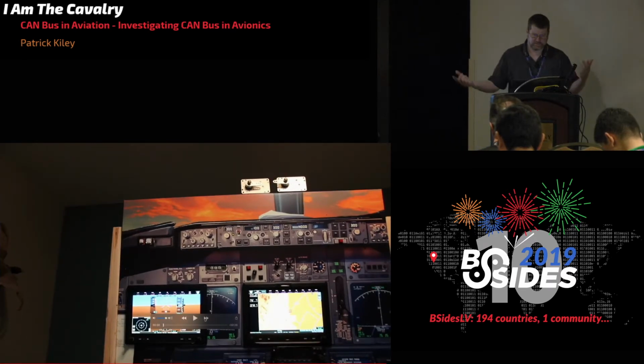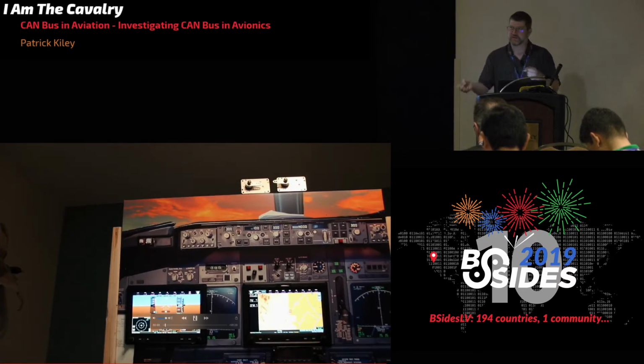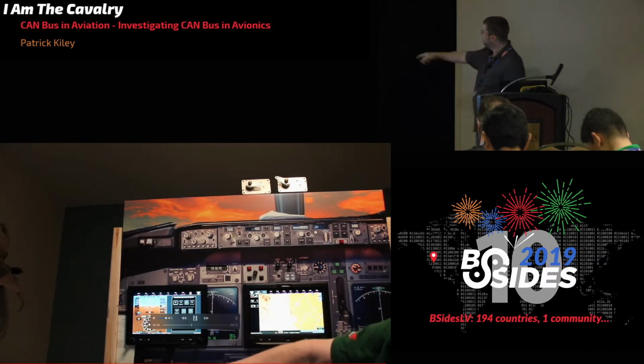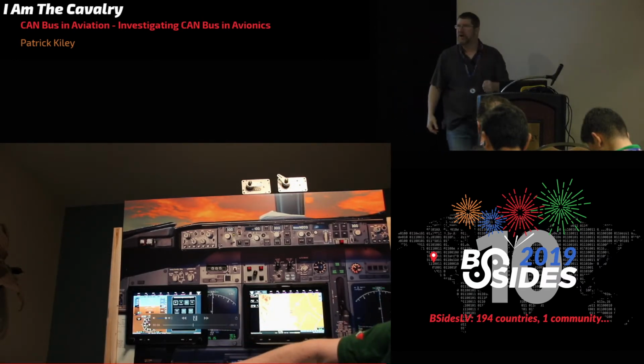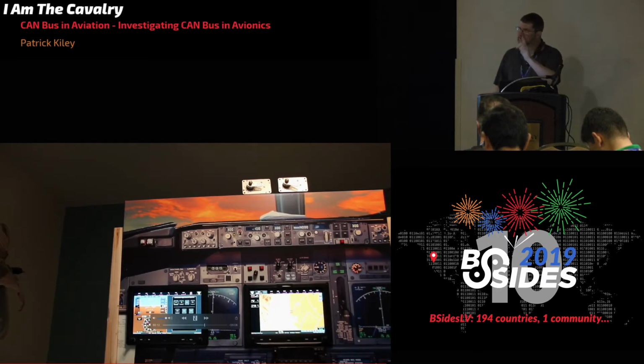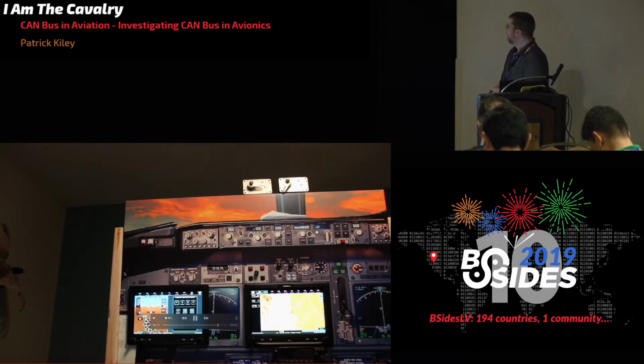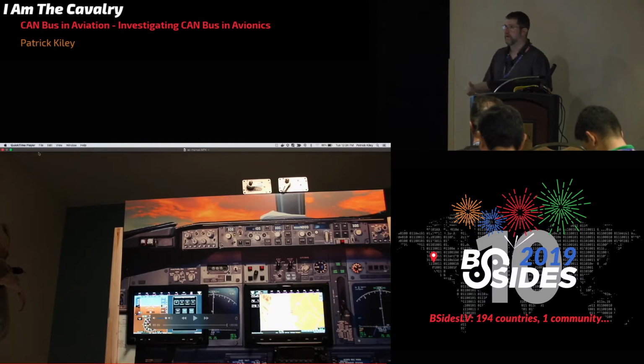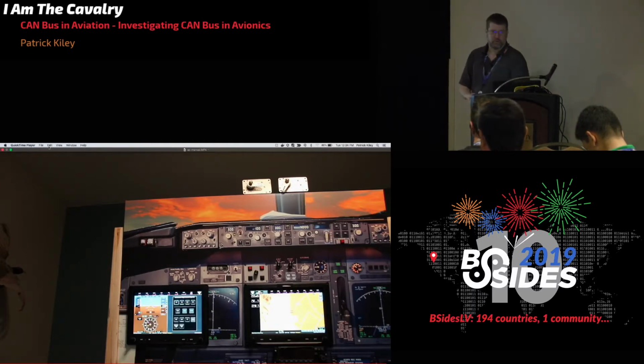So you can imagine you have a pilot in charge of this. Now all of a sudden the controls are fighting themselves, and he's telling the autopilot to turn off. There's usually a button right on the control stalk or a button up on the display to tell it to turn off, and they're not turning off because the bad guy is sending a message saying stay on, stay on, stay on, and how terrifying that could be. Really the only solution at this point is to find the circuit breaker for it and pull power from the servos, assuming it's been wired appropriately to do that.